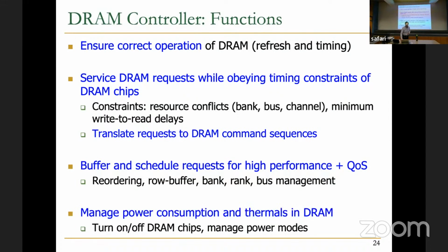And then there's power consumption and thermals. This is becoming increasingly important, actually. So you need to manage power, especially with 3D stacked memories, because you have logic and DRAM and then many layers of DRAM. And because of the structure, heat has nowhere to escape, essentially. As a result, this increases the power consumption.